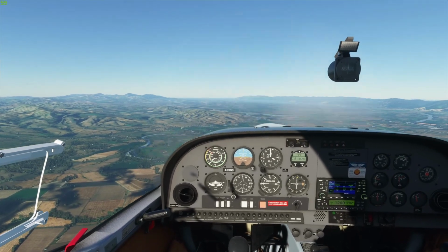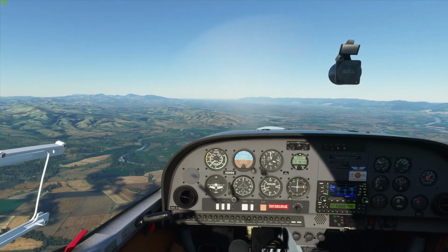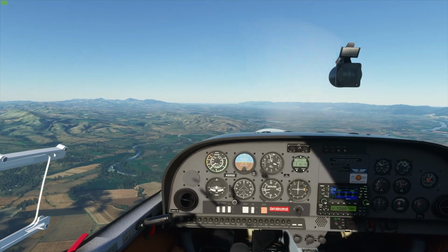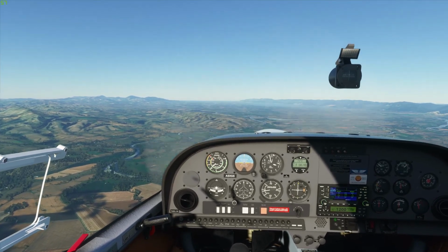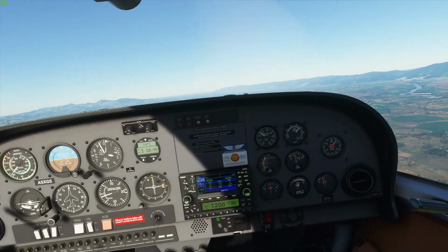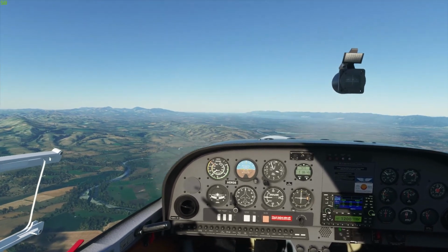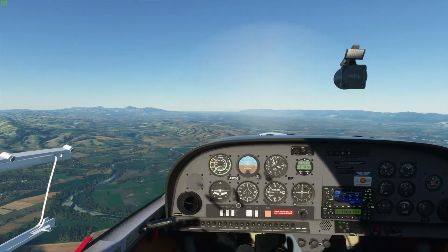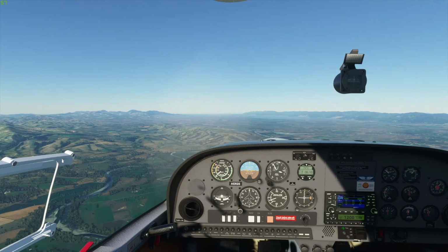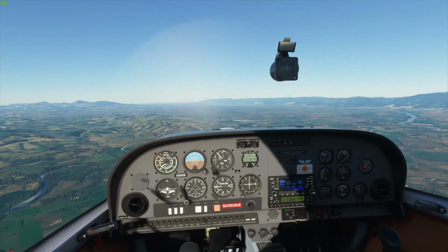Okay, I'll bring the power back now to 23 inches of manifold pressure, and I'll reduce the RPM to 2300 as well. So that's going to be pretty much it's a bit hard to tell in this light, but just around there somewhere. Okay, and now there's going to be a trim change required, and we're sitting at 105 knots. Try and get back to 3,000. T's and P's are still in the green.